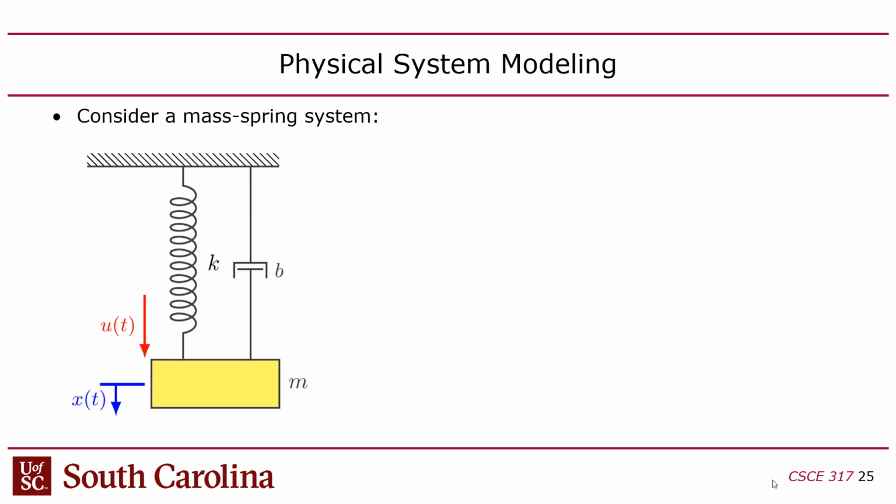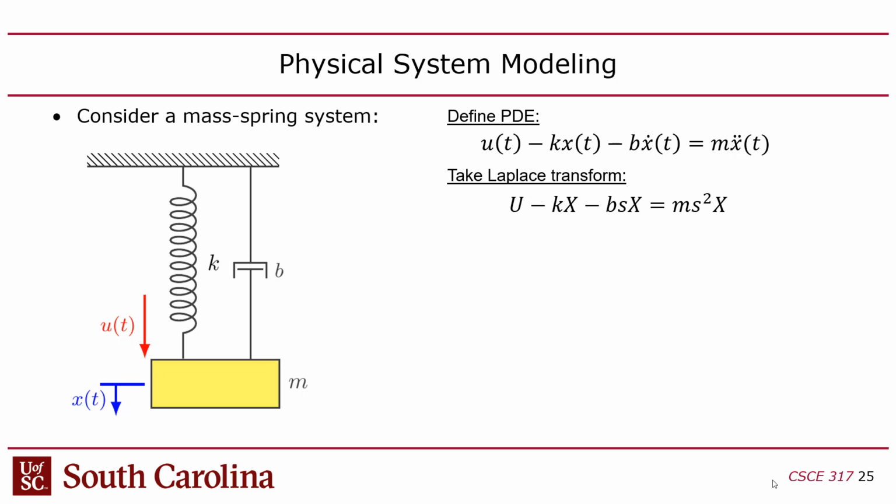springs have a damping factor as well that you don't account for in that system. So it's not just the spring constant. You have this damping factor B. And the damping factor is what ends up making this stable, right? So the way you account for that is it's just another term.